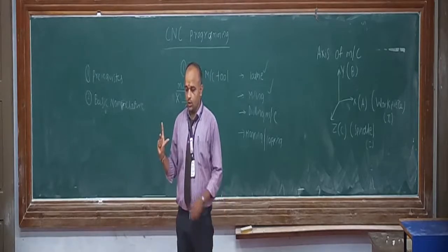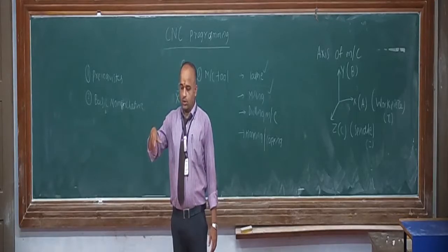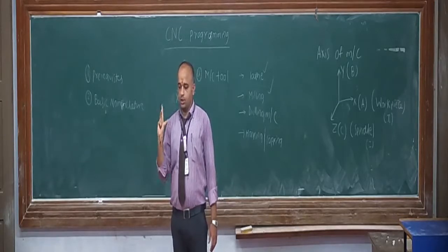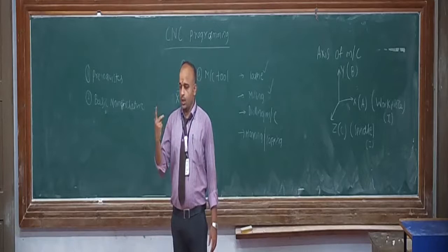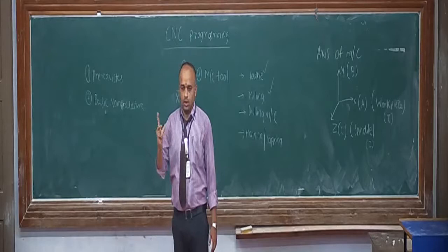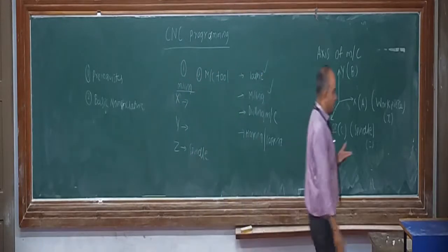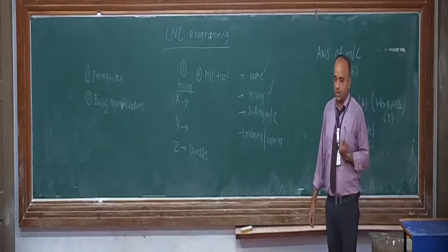And just also understand the rotations. Rotation about the x: clockwise is positive, anti-clockwise is negative, and again positive, negative for the others. So now why is this very important? Because we have done only 2D machining. 2D machining in the sense means what?